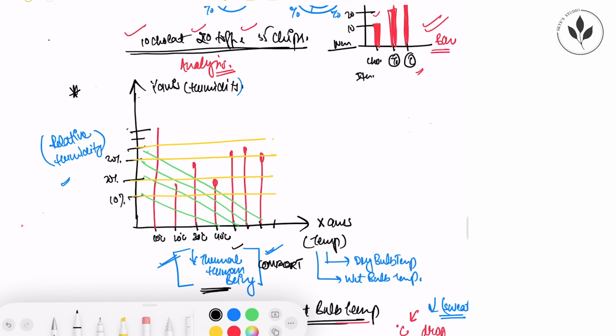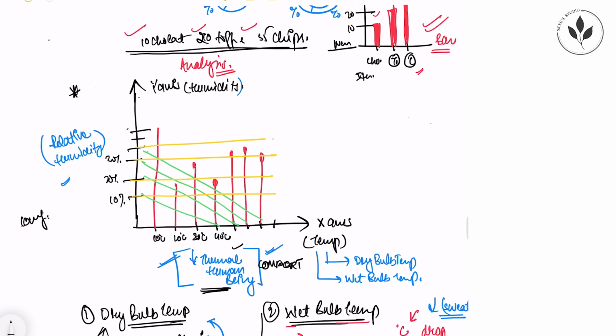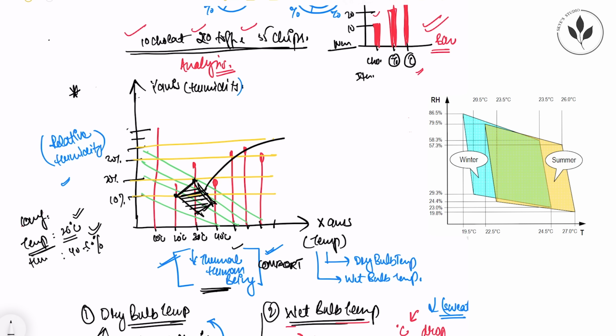horizontally. We have certain comfortable zones for temperature and humidity. Up till 26 degrees Celsius, it's comfortable for human beings to stay in this temperature. You will neither feel too hot nor too cold. Humidity from 40 to 50% is appropriate for human comfort. So when we find these values somewhere here, we get a zone which is for the maximum comfort level of a human being. So this zone becomes the comfort zone for a human being, and this is the main purpose